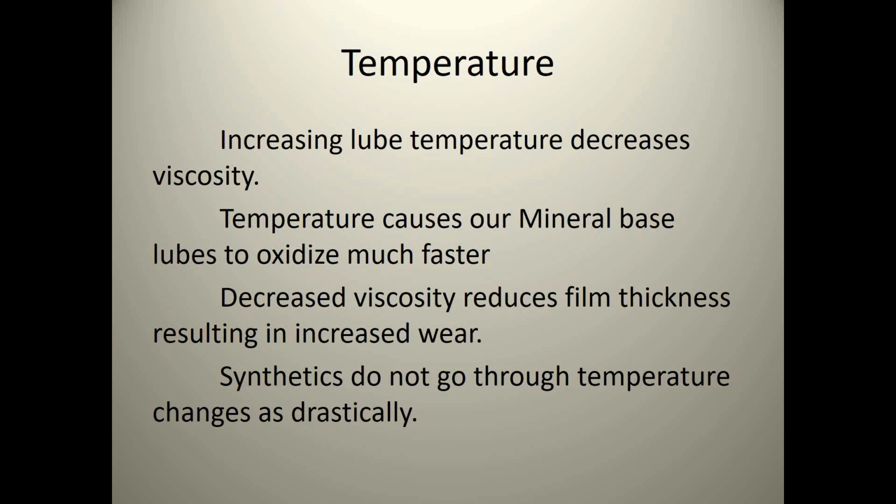But let's look at this first temperature failure mode. As lube temperatures increase, viscosity decreases. We looked at some of those curves, and I'll show you one again today, but it is very important to remember that in mineral-based lubes, temperature has a huge effect on viscosity, and viscosity has a huge effect on your equipment life. So as things get hotter, as things get colder, you have to watch what that viscosity is doing.